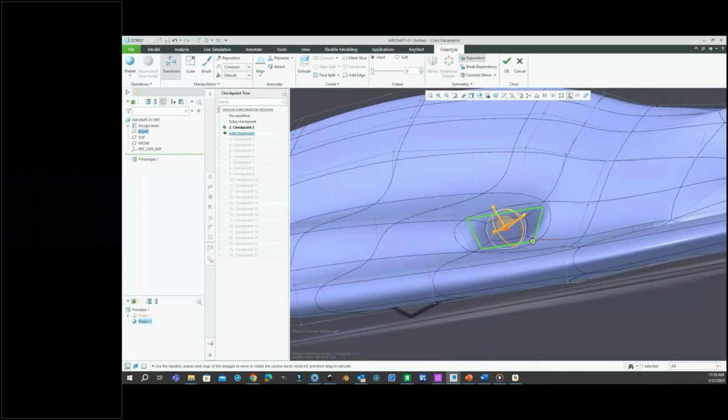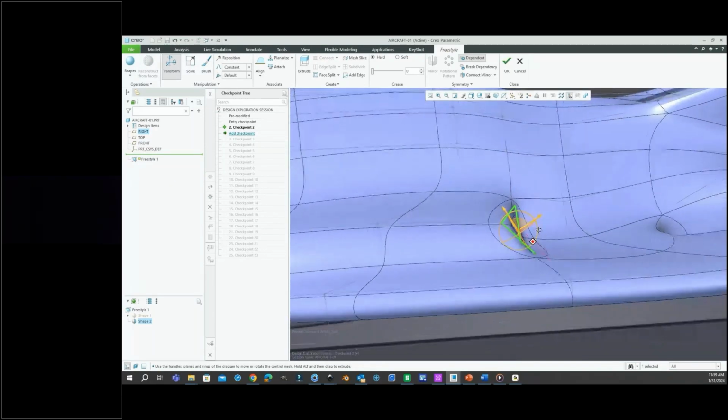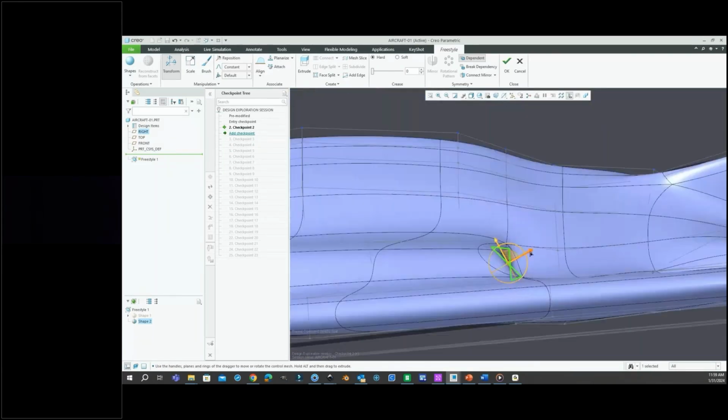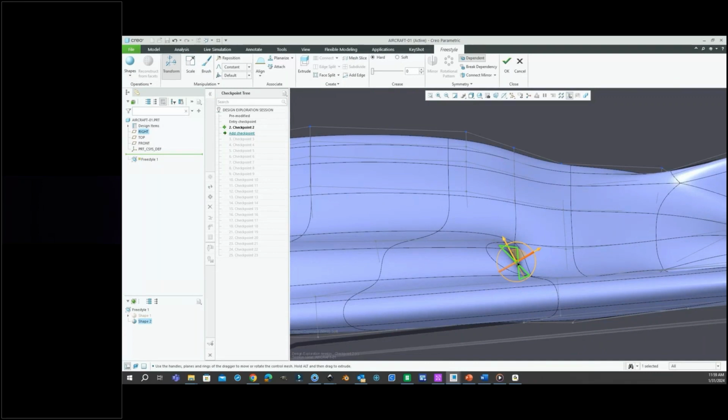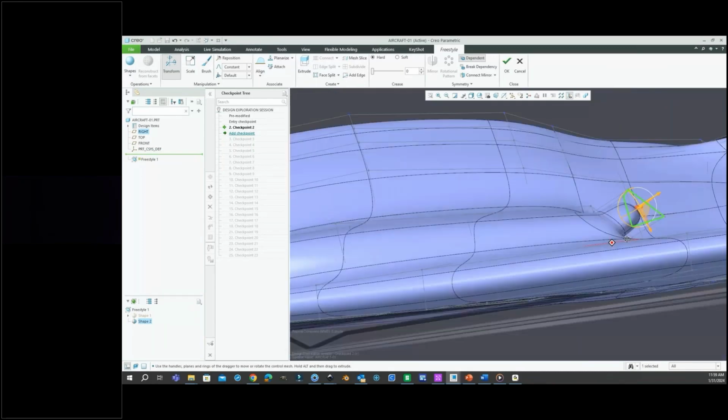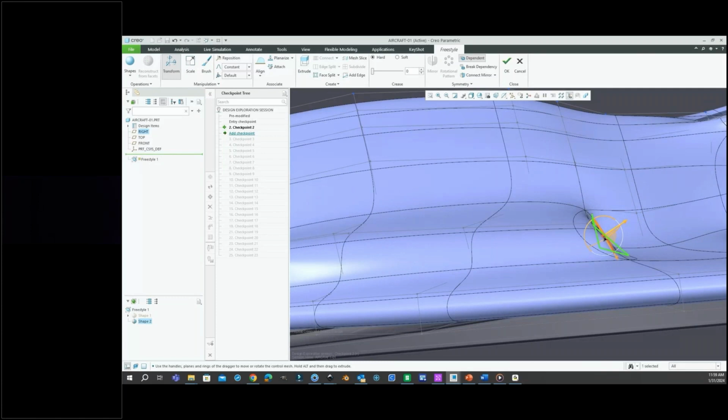All right. You can also adjust the orientation of your translation arrows. So, say for example, you're like, hey, if I select this arrow and I extrude inside of this, it will be at the wrong angle. You can actually right click here and say reposition. And then you can reposition where your arrow is and then uncheck the reposition box. And then you can do your extrusion, for example, in that direction. So let's go ahead and I'm going to take that back here, reposition.